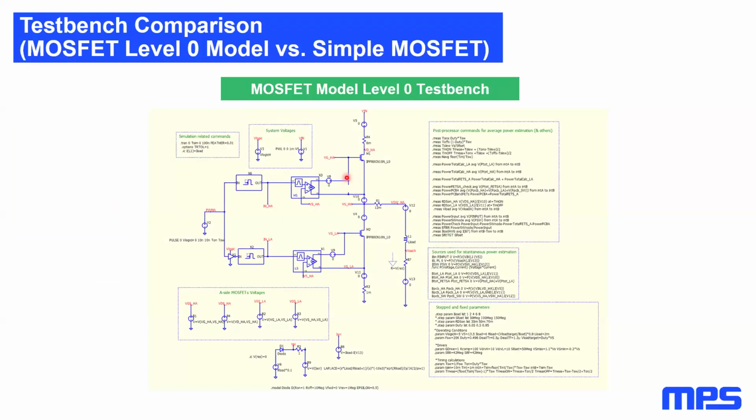The time transient simulation outputs a dataset of currents and voltages of the circuits, and the power dissipation can be calculated at simulation time step by time step, by multiplying currents with voltages using behavioral sources. These behavioral voltage sources will then output power data over time, which can be post-processed via the QSpice measurement statements in order to determine average powers within an integer number of PWM cycles.